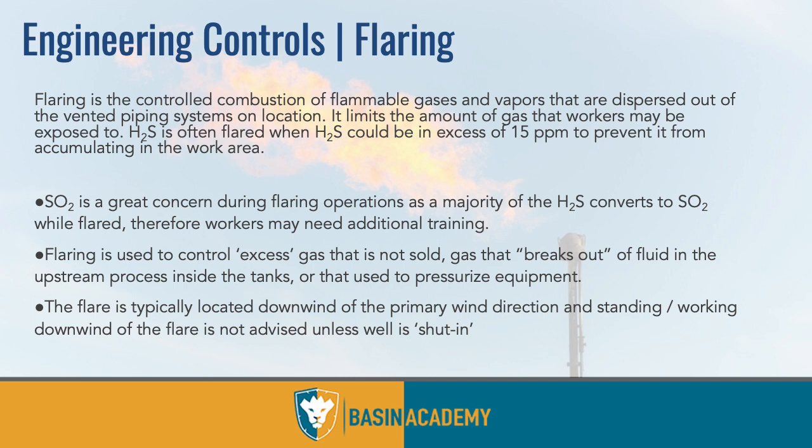So just keep that in mind. At that point, SO2 is the greatest concern. So those flare stacks being higher is better, right? Because both SO2 and H₂S, when they come in contact with wind, there is a high dispersion rate. So when wind hits it, boom, it goes from high percentages to very low parts per million quickly.